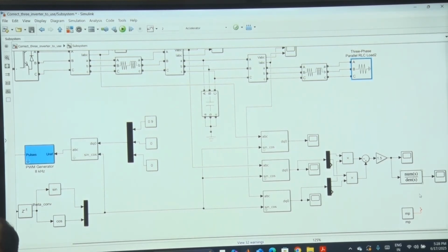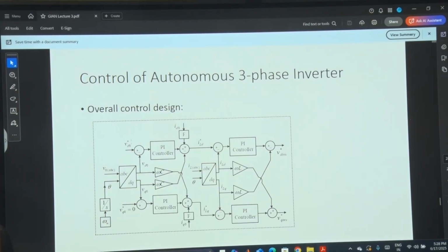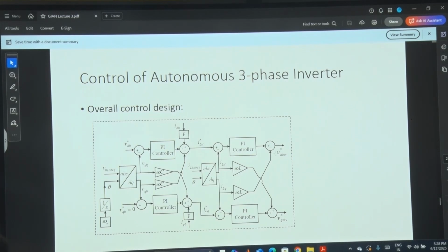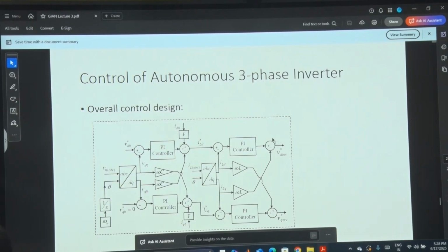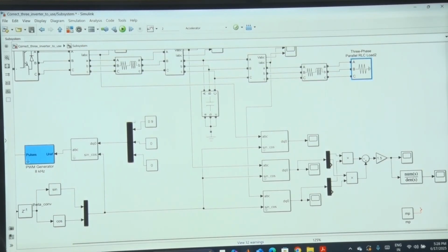Now you know, step by step we are building the complete closed loop of the single inverter. We calculated the power. Now what is left? The droop, the voltage controller and the current controller. This is what we discussed. If you remember, from here, the voltage controller VOD star minus VOD, then the current controller, and what we get is this VD inverter, VQ inverter, which we then multiply by 2 by VDC to get MD, MQ. Those MD, MQs are here.